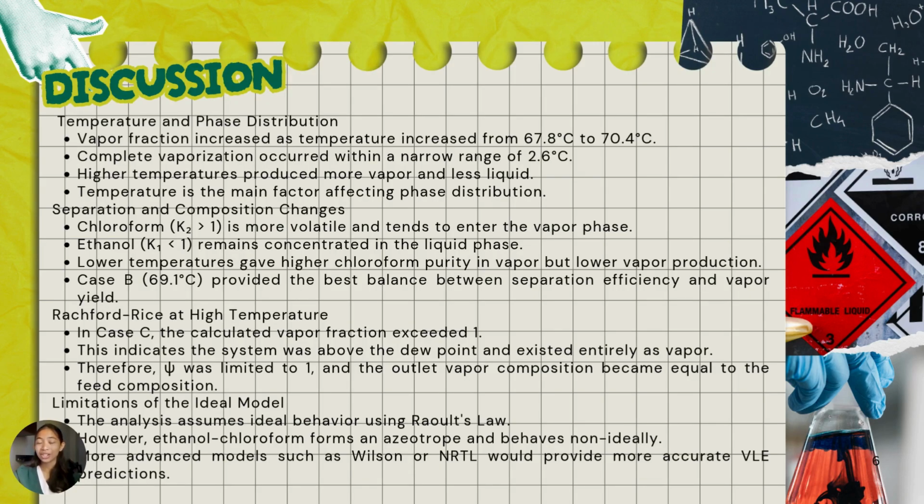This shows the engineering trade-off between purity and yield. Case 1 gives high purity but very low volume. Case 3 gives maximum volume but no separation. Hence, case 2 is an optimized, balanced middle ground.